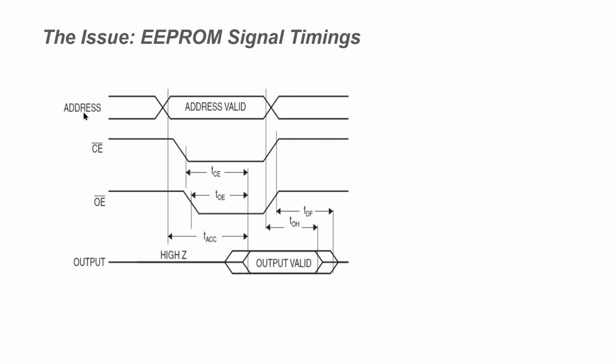Up here are the signals driving the address to the EEPROM. We provide a 16-bit address to the EEPROM, and then it outputs 8 bits of data at the output pins. This shows the address signals going up and down, the bits going on and off to construct the address. And here is the point where the address signal lines have stabilized and the address is valid.